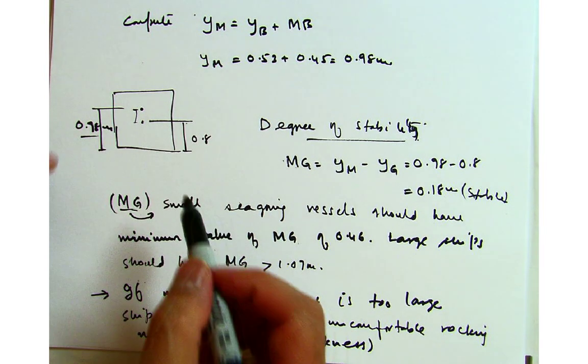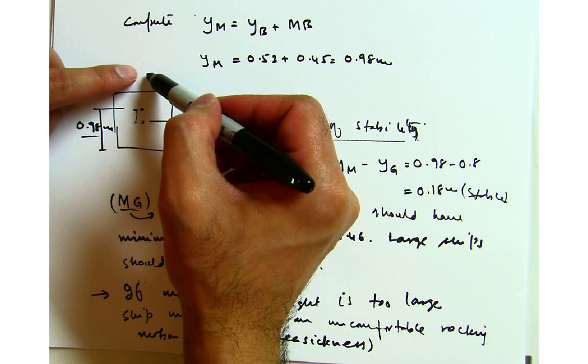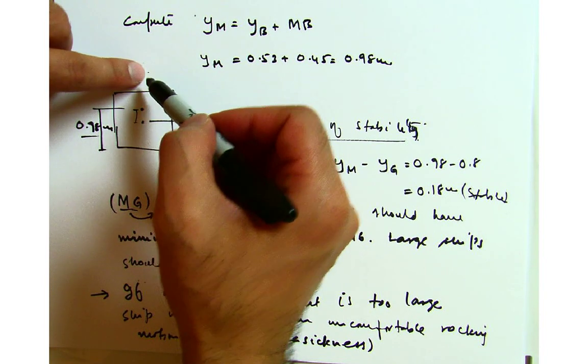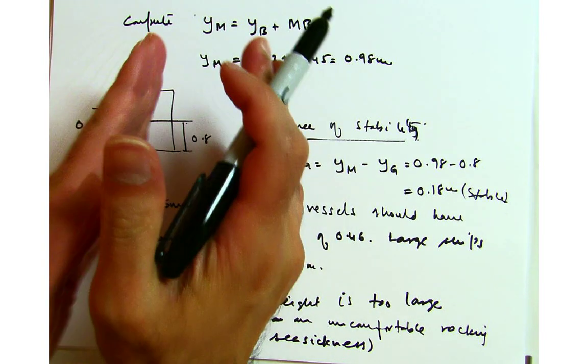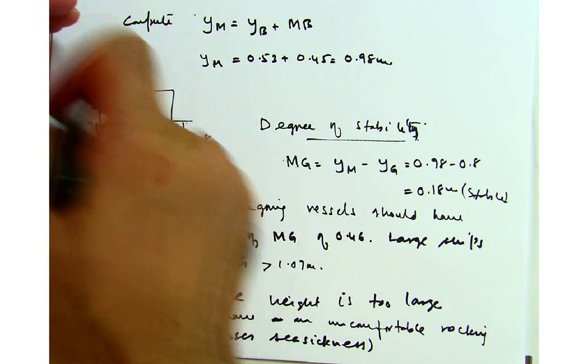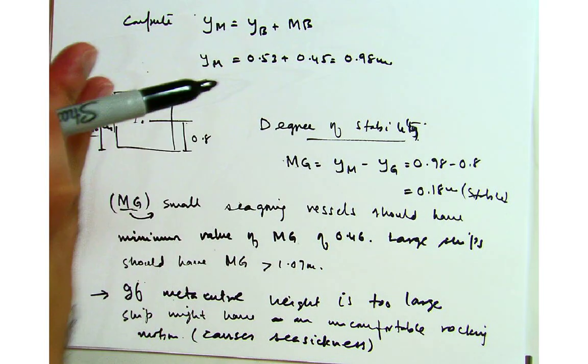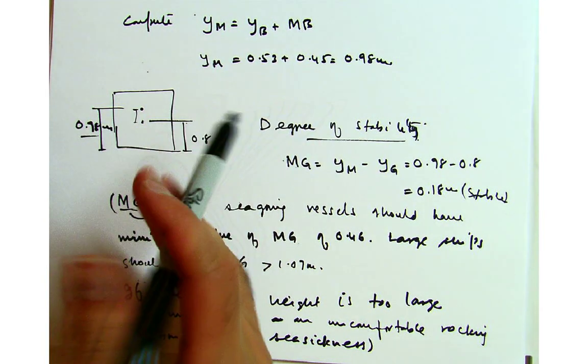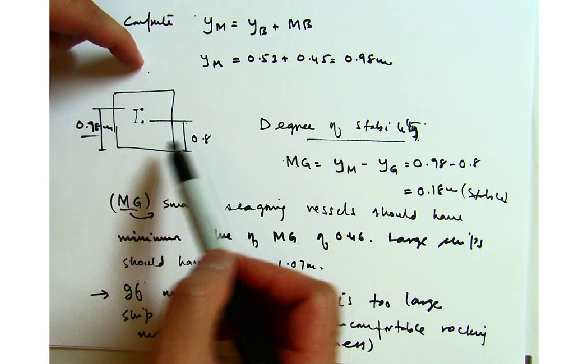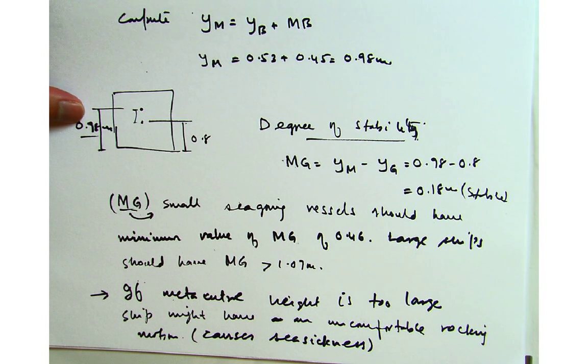You can think about it like the higher this value of M would be, when it tries to stabilize, it basically creates more rocking motion. It will create more rock, but at the same time the degree of stability will be even higher because you have a much higher metacenter. Alright, so the next thing is, again it's more of a discussion, so let's look at the stability curve.